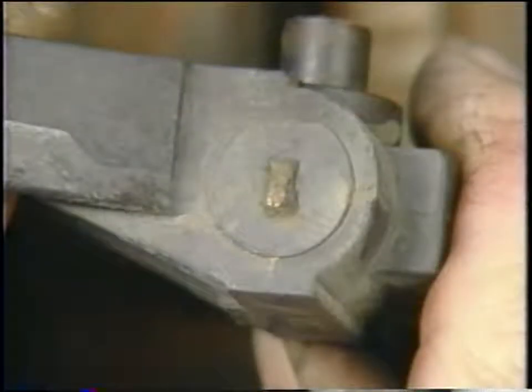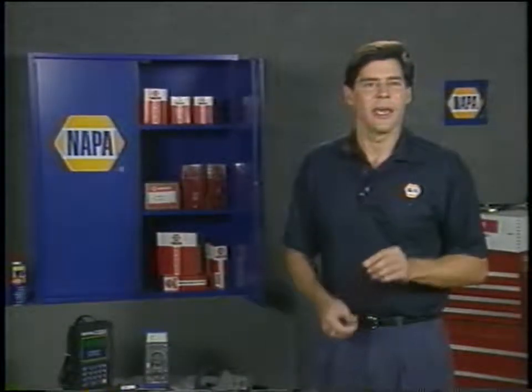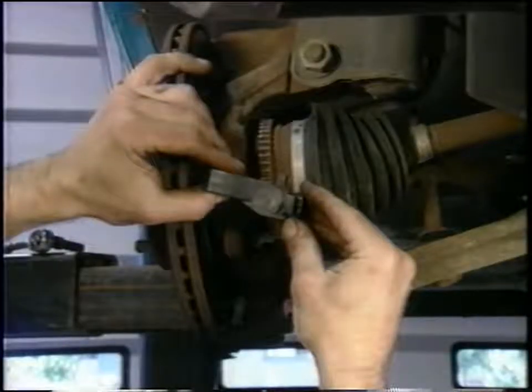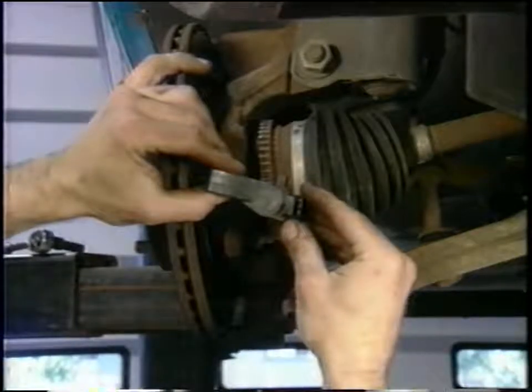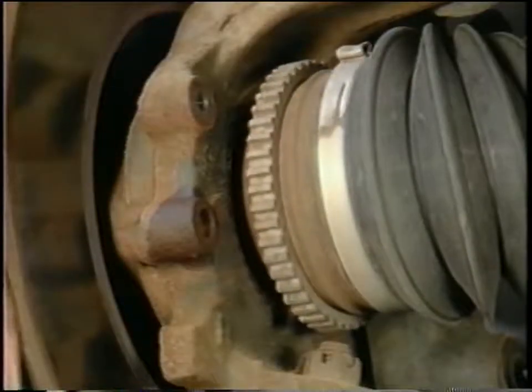Wheel speed sensors are magnetic and can attract metallic debris. This can be just as much a problem, if not more of a problem, for speed sensors that are mounted in the differential or transmission. Metallic debris from normal gear and bearing wear, as well as metallic particles from automatic transmission clutch linings, can be carried by the oil to the sensor. As debris builds up on the sensor tip, it reduces the sensor's ability to generate a reliable signal. Removing and inspecting the sensor for this type of contamination, therefore, is recommended if a sensor problem is suspected.